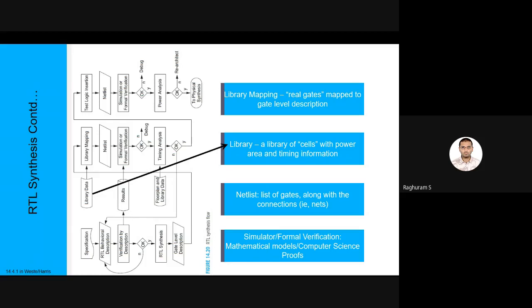The same way, we don't have our function directly, but we might be able to implement it using two different gates. So maybe an 8 input AND can be built using two 4 input AND gates, or if 4 input is not there, maybe two 3 inputs and one 2 input. At least that much will be there.